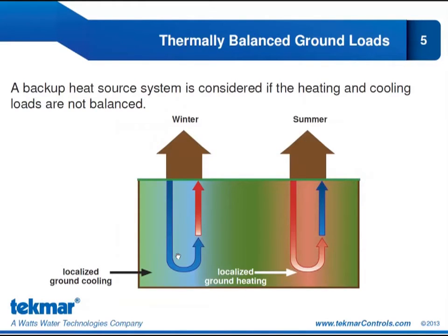Now, for those of us living in Canada or those of you living in the northern United States, you would experience a heating dominated area where a backup heat source would be recommended. This makes sense because the geothermal heat pump can take advantage of part load operation, so we don't have to worry about sizing our heat pump and geosystem for 100% of the load. We rarely see outdoor temperatures where that is required. So instead of upsizing our ground heat exchanger and the capacity of our heat pump, what we can do is take some of the pressure off our heating load with the backup heat source and maintain the thermally balanced ground loads.